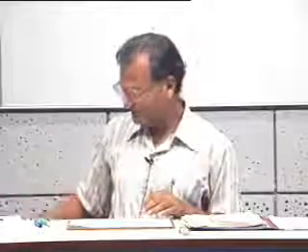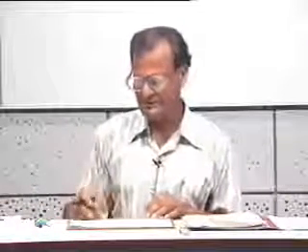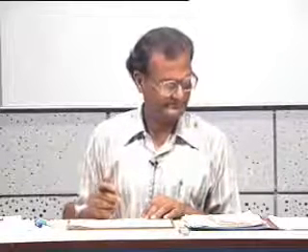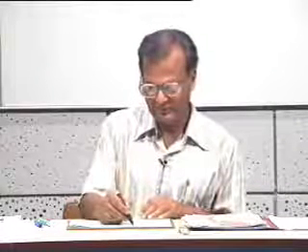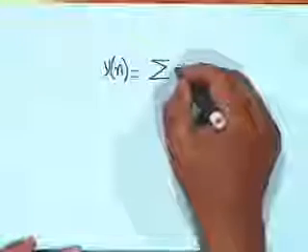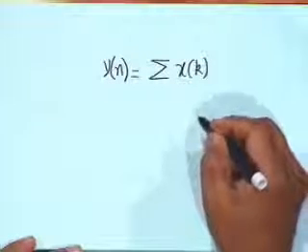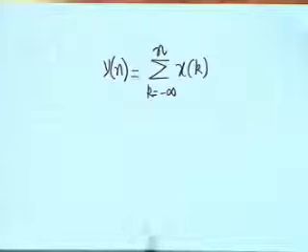There are many ways of looking at this. Let's take a little more complicated example and see whether that example system is invertible or not. And this example is, let's say, y of n. To bring variety into experience, we will switch back between continuous time and discrete time. Let's say y of n is the summation of x of k, k equals minus infinity up to the present time n. Is it a memory system or a memoryless system?